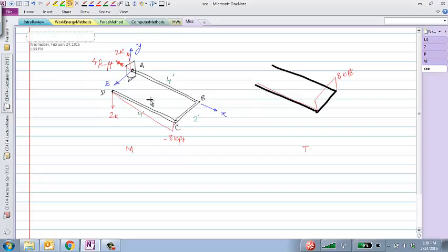But another way to look at it is this: if you remember back from statics, the concept of equivalent forces and moments. If I move this force from this point to this point, I also need to apply a moment in order to do that, and that moment was 8 kip feet. So the original problem is equivalent to this problem that I just drew here, right?